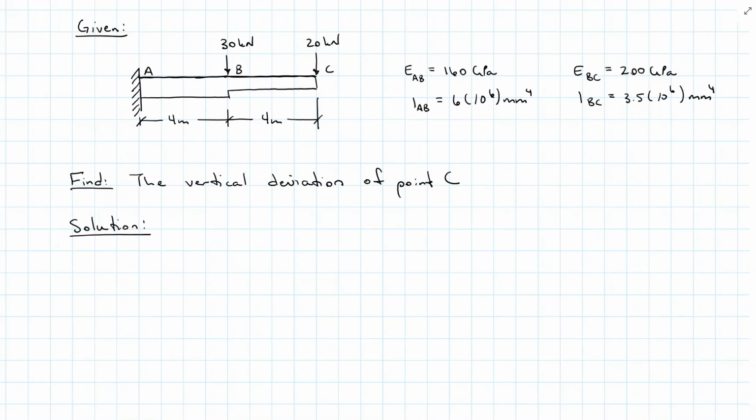So again, I'm going to stick with my game plan of starting with the elastic curve. And what's nice with a fixed end is a fixed end prevents rotation and translation. So that means it's going to come out flat here before it starts to bend down under the load. And what we are looking for is how far does C move down, deflection C.